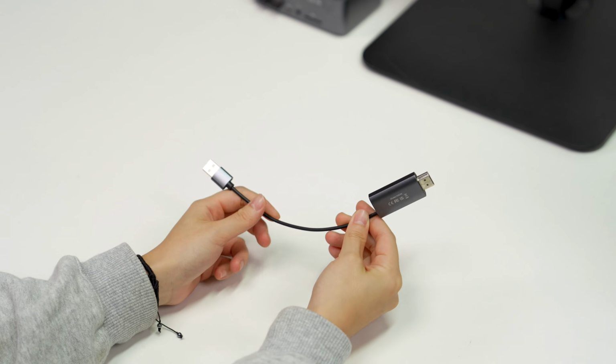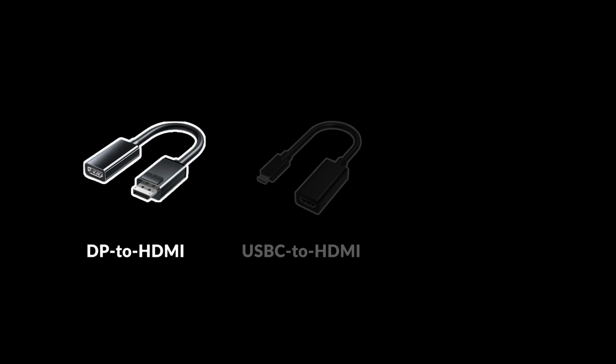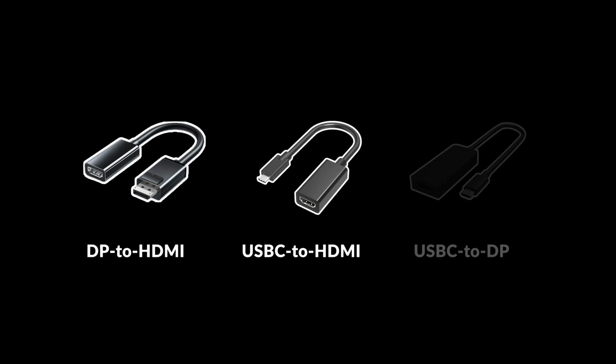Number 5. Are you using an adapter or adapting cable for video transfer? An adapter in your setup can bring compatibility issues. Also, adapting cables like DP to HDMI, USB-C to HDMI, and USB-C to DP often work in one direction. Make sure it's the right direction for you.